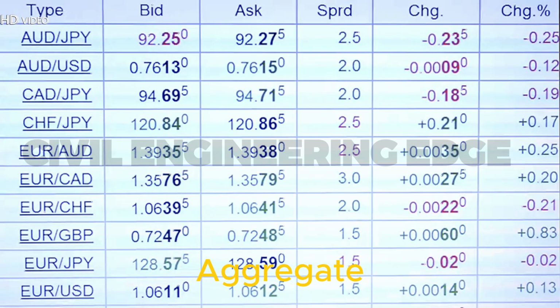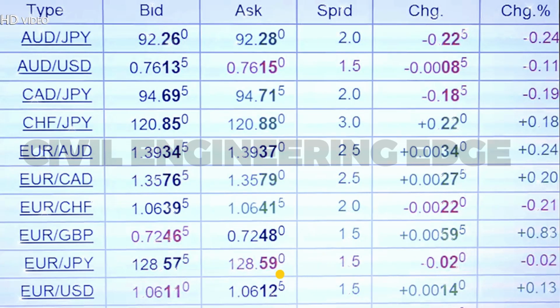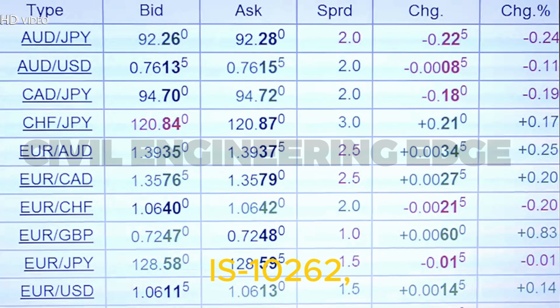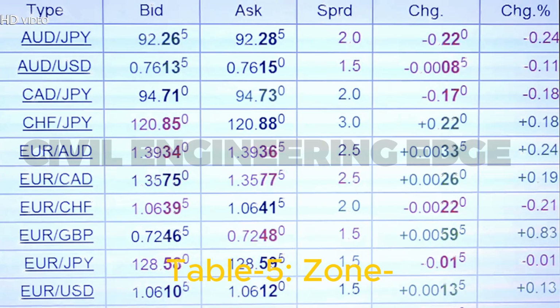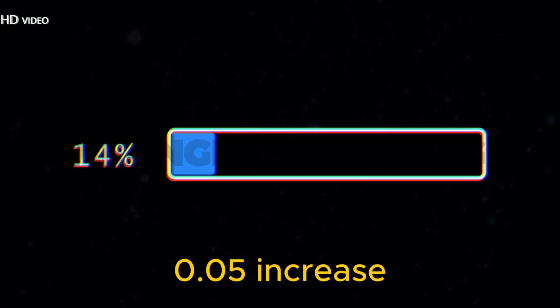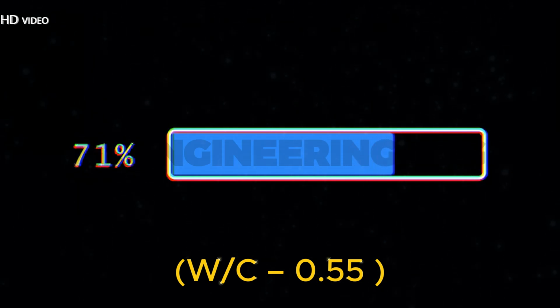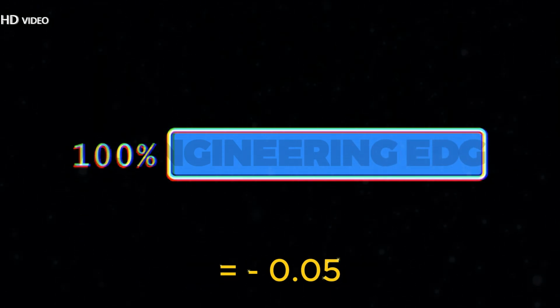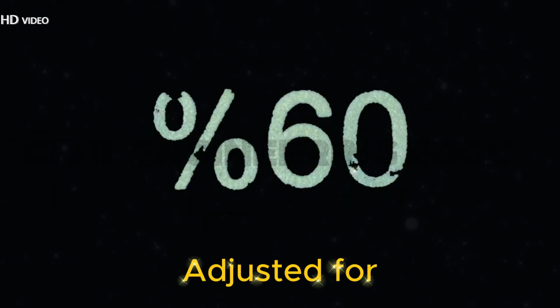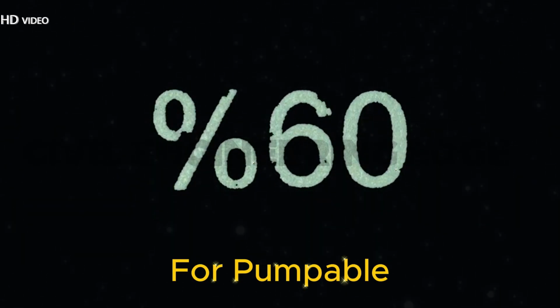5. Aggregate proportioning, CA, FA ratio. IS 10262, Table 5, Zone 2 sand equals 0.62. For every 0.05 decrease in W/C ratio, increase 0.01.